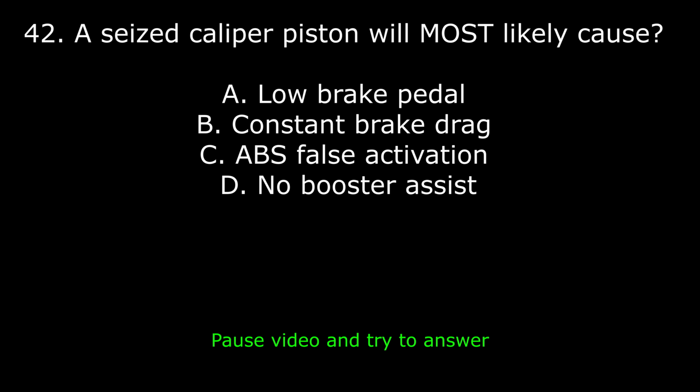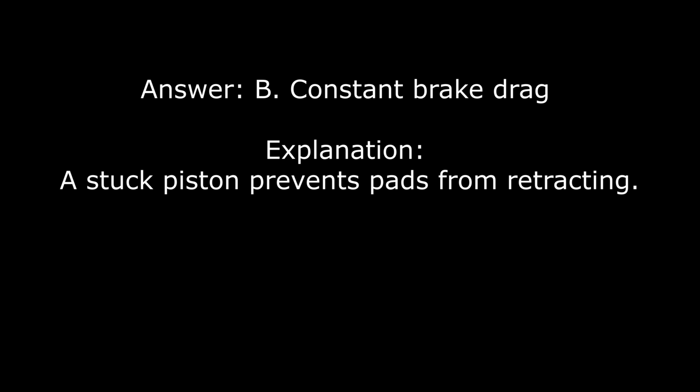42. A seized caliper piston will most likely cause: A. Low brake pedal, B. Constant brake drag, C. ABS false activation, D. No booster assist. Answer B. Constant brake drag. Explanation: a stuck piston prevents pads from retracting.